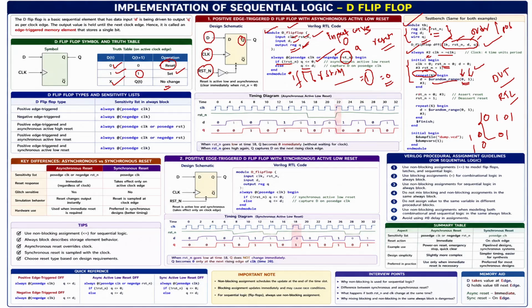After that, I'm setting the reset condition again and then de-setting the reset condition after some time units. Then again I'm changing the values. So I give different values here, and here also. Every time you give different values, you need to set the reset condition and then de-set it. During the reset condition, all the values should be 0. During the de-setting of the reset condition, we manually give the values. This is the waveform representation: $dumpfile dump.vcd, and $dumpvars, variable change declaration will be considered here.